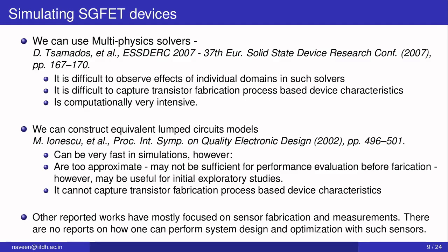Further, it is very difficult to capture the transistor fabrication process. You can define the device by the implants, depths and so on, but you cannot really simulate the process and then simulate the device that results from that process. Fabrication process step simulation is quite difficult to capture in these kinds of solvers, in addition to the fact that they are computationally very intensive, because the equations involved are very diverse.